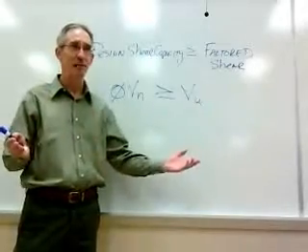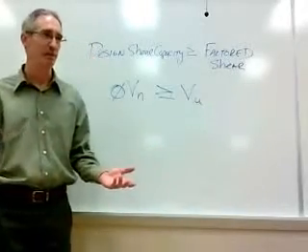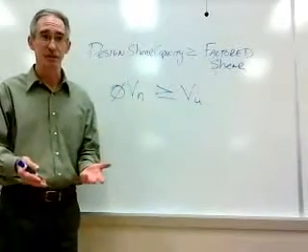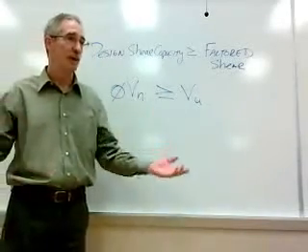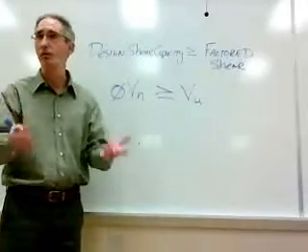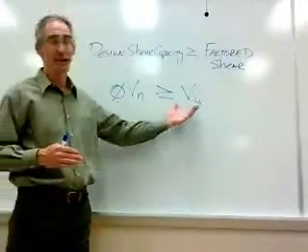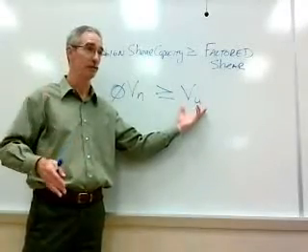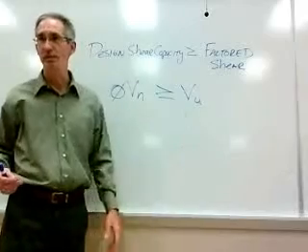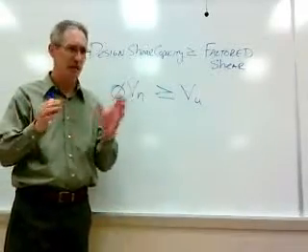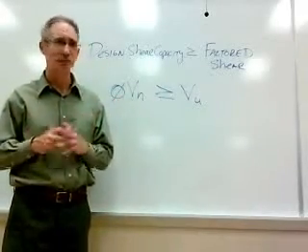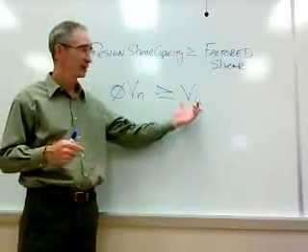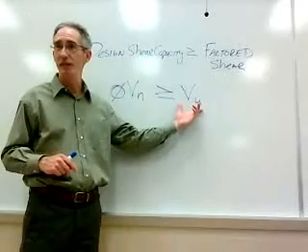You might have a beam, you might have loads on that beam. Those loads, if they're service loads, would have to be factored. You'd solve the reactions, you'd do a shear diagram. That shear diagram is showing you V sub U, factored shear, across the whole beam. Now we're going to be interested in certain segments or certain places on the beam where V_u is, but generally speaking, you already know how to do this.